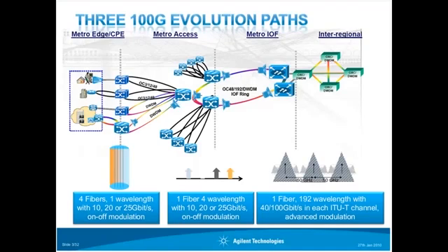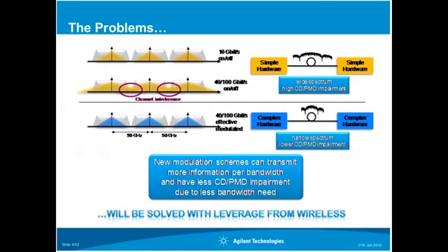What we are addressing more is the long haul systems. In the long haul systems, we will see polarization multiplex signals which add up to 100 gigabit per second in one ITU channel. Essentially, the challenge in long haul systems is to transmit 100 gigabit over a 10 gigabit infrastructure. That 10 gig infrastructure was installed looking forward to 40 gig, so it's not that bad, but people did not really consider 100 gigabit at that time. So the challenge is to squeeze a 100 gigabit spectrum into maybe 50 gigahertz channels. You only have the 50 gigahertz bandwidth available, and you somehow have to compress the spectrum of your 100 gigabit signal into that.